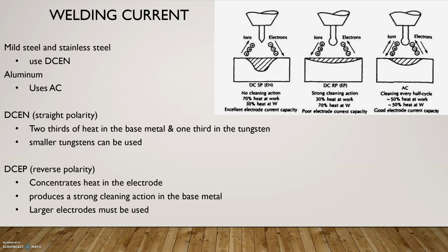This is not used for TIG welding because the heat will consume the electrode and you won't be able to weld. The main thing direct current electrode positive is used for is for, very briefly, balling a tungsten for welding aluminum.